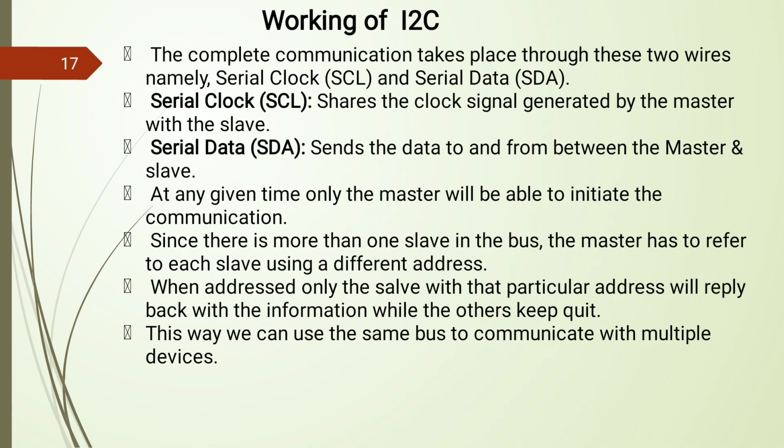After that, we discuss some points related to that. So only two lines, SDA and SCL, are used. The next point regarding I2C is accessing multiple slaves. Here I2C uses a frame which includes the address of the different slaves. The address is provided with the help of either a 7-bit address or a 10-bit address.